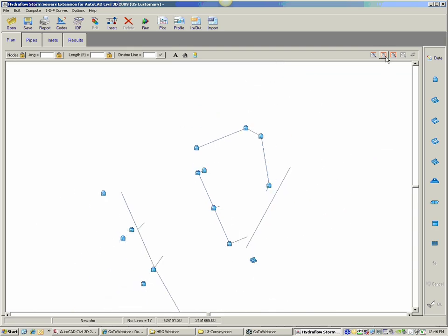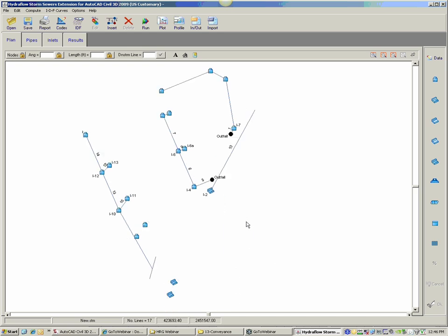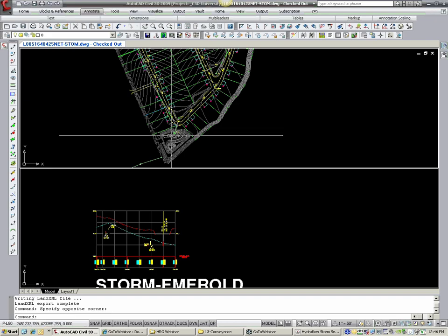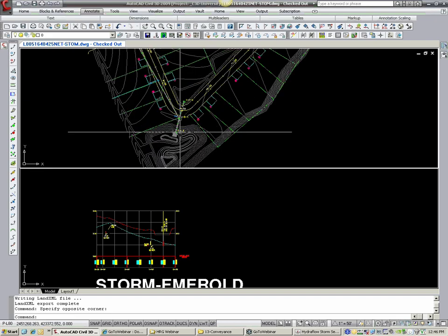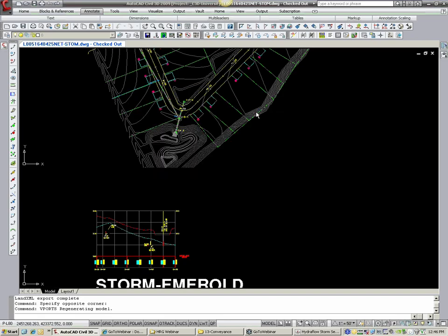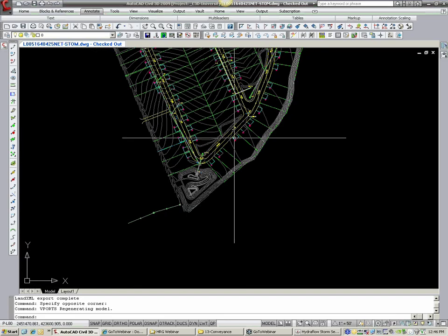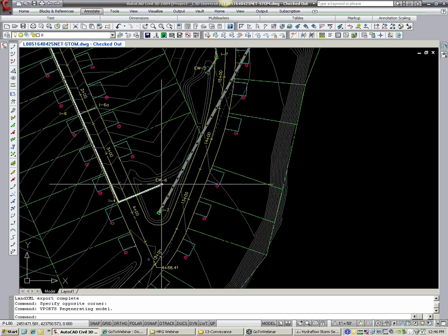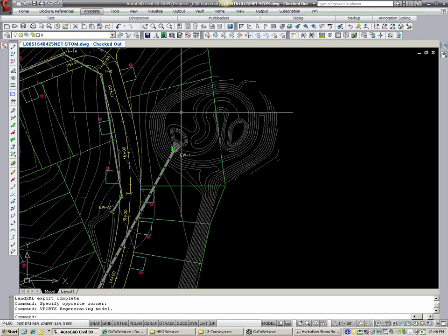Now, typically in a design like this, this outfall. It's not the outfall of the basin; it's the outfall of the conveyance system. So let me switch back over to Civil 3D here and show you what I'm talking about. That outfall is here, so the end wall going into the basin. Let me switch my viewports back to make a bigger view here. That's the end wall going into this basin down here. Then I have this end coming. This is actually an upwell coming into this rain garden, and then it takes over to this basin over here.